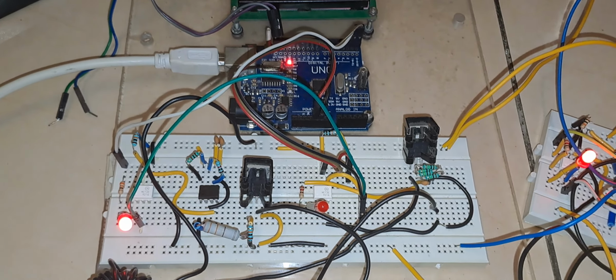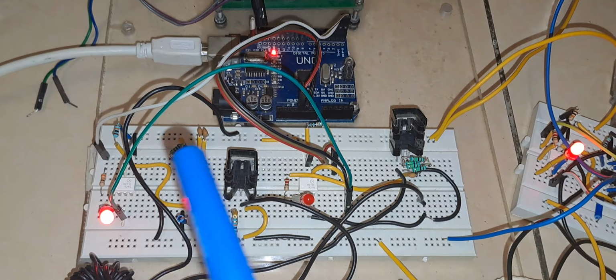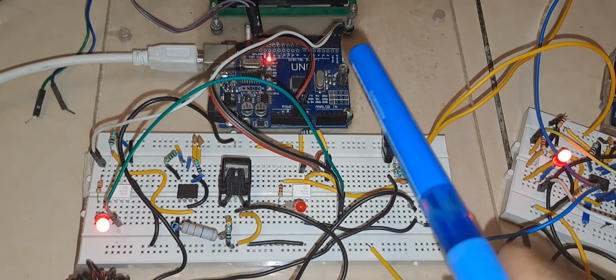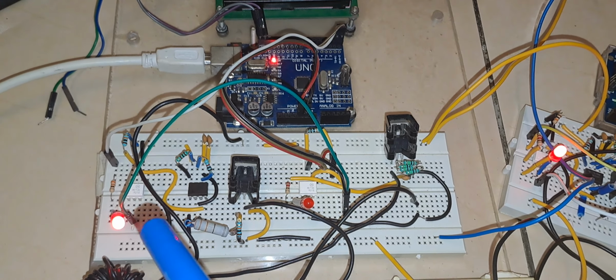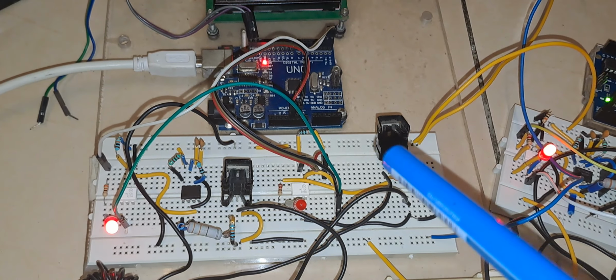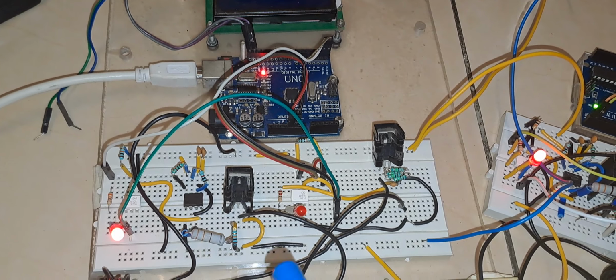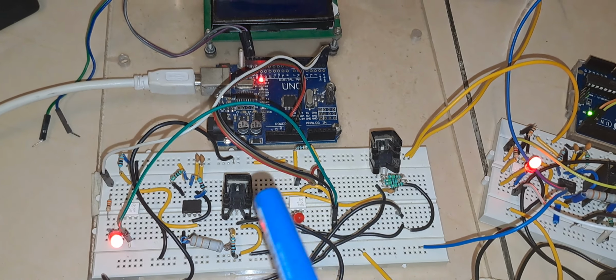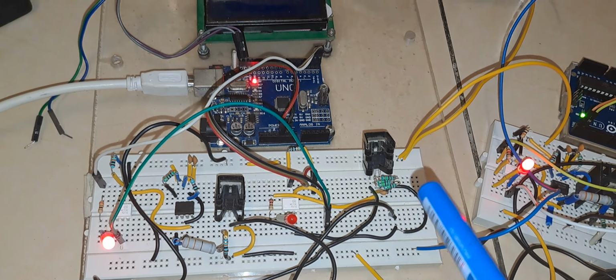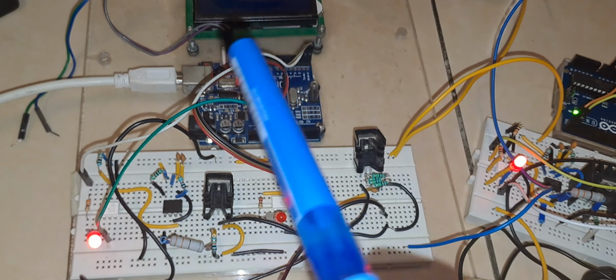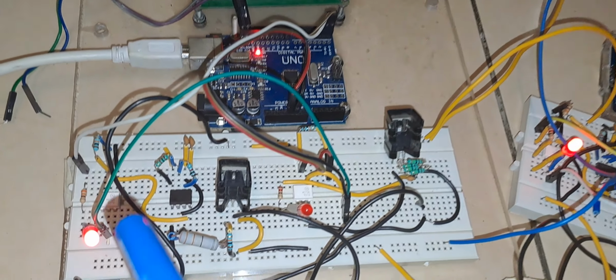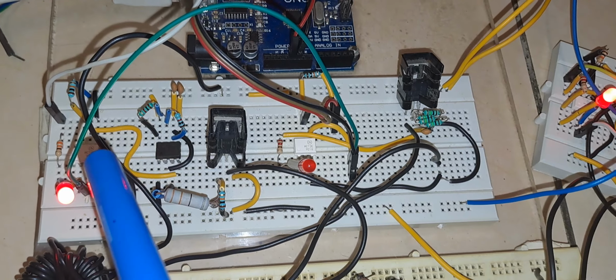As you can see, this is the transceiver module, and here you can see the Arduino is sending data to the transceiver module, and it is receiving data from the transceiver module. The transceiver module has two parts. If I draw a line here, this will be the transmitter end and this will be the receiver end. The data from the transmit pin is coming here, and it is optically isolated. You can see there is an optical isolator.